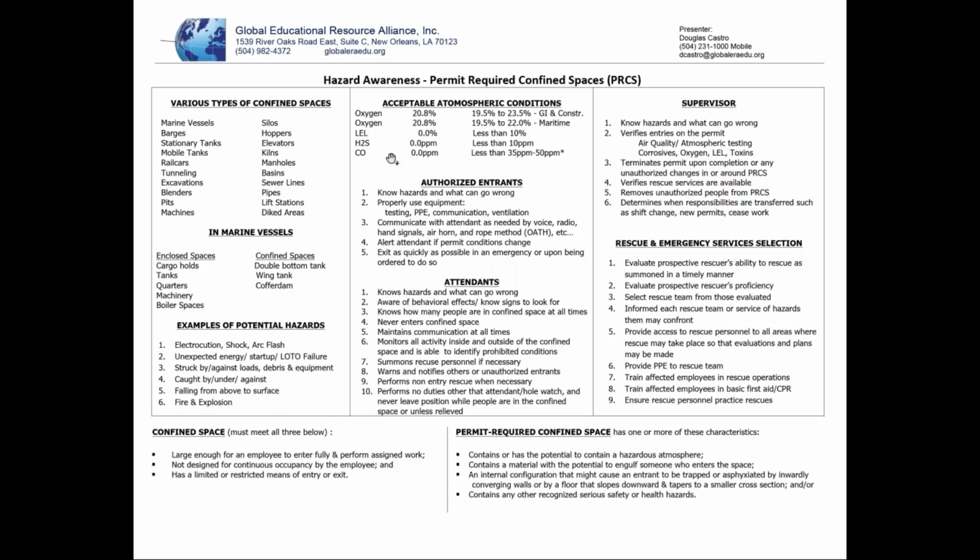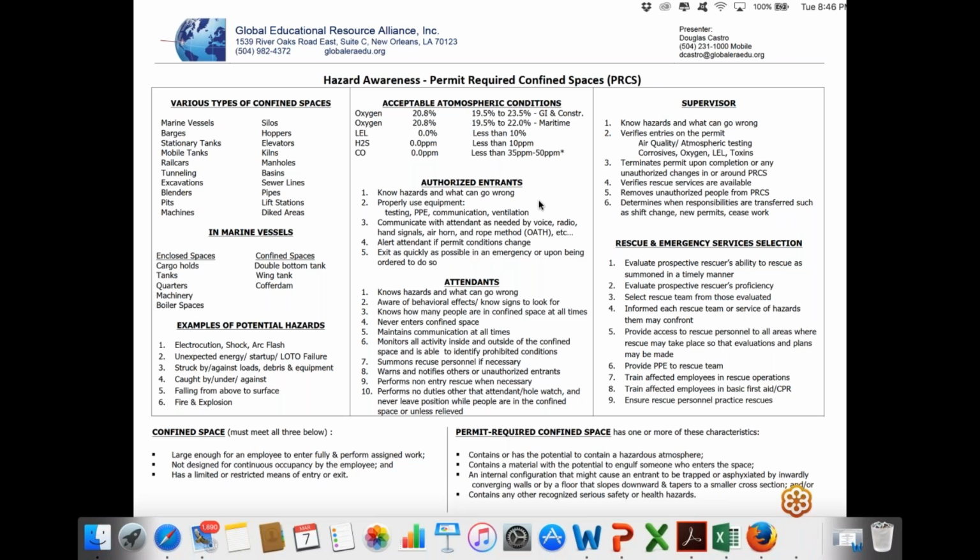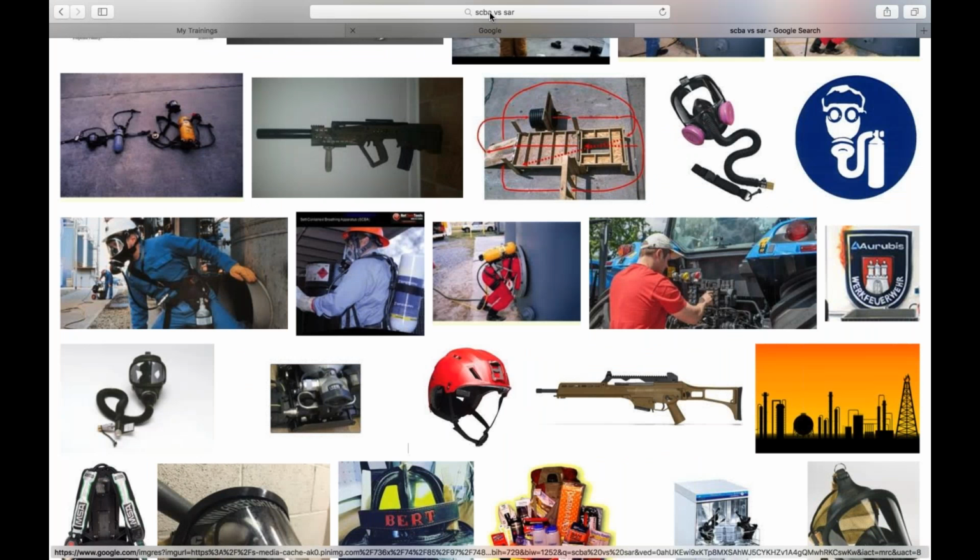So let's say in a confined space, I'm going back to page 7.6 now. If a confined space has to be entered in an emergency, we want to take certain precautions. All lines containing inerted, toxic, inflammable, or corrosive materials have to be disconnected or valved off before entry. And I'm talking about like off of a tank or off of a refinery or a unit or something like that. So we have to make sure that all the gases. So let's go ahead and go to that here on the website.